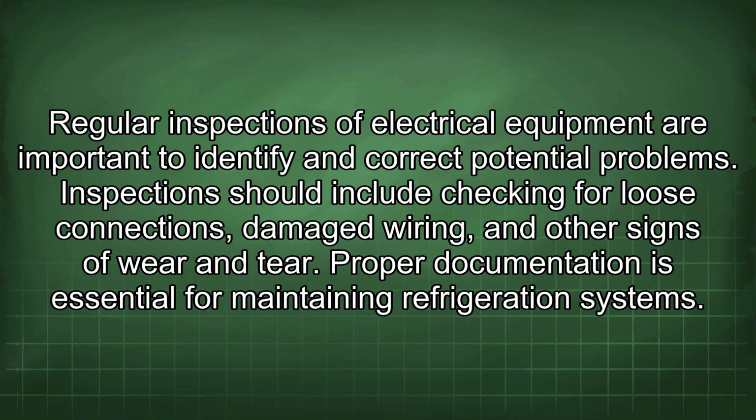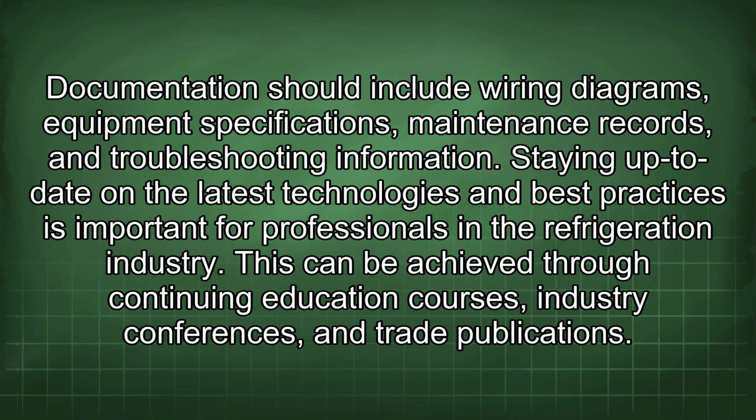Inspections should include checking for loose connections, damaged wiring, and other signs of wear and tear. Proper documentation is essential for maintaining refrigeration systems. Documentation should include wiring diagrams, equipment specifications, maintenance records, and troubleshooting information.